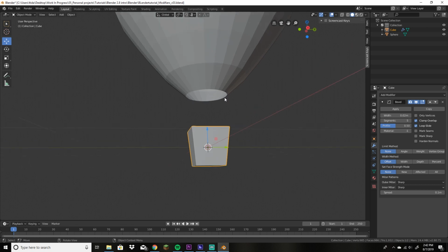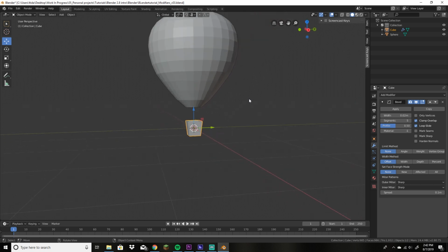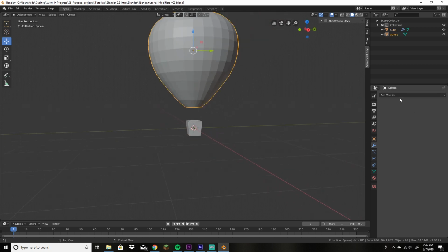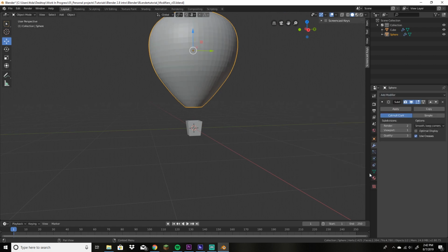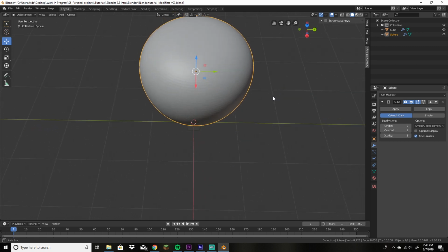Same with this. Like right now, this is infinitely thin. We'll want to give this some thickness there so that something can be there to catch the light. But first, before we do that, I want to add a subdivision surface modifier. And that's just going to kind of round that out a little bit. We're also going to push the viewport to be the same as the render. They're separate so that in the viewport it could be a lower resolution than the render, but we really just want them to be the same for now.